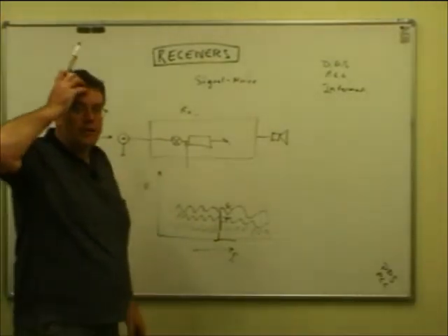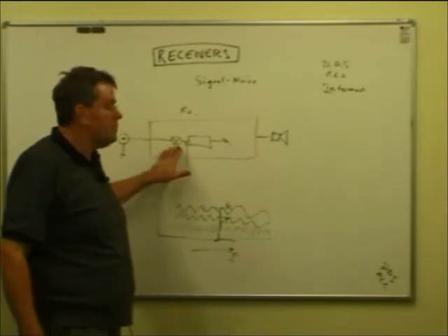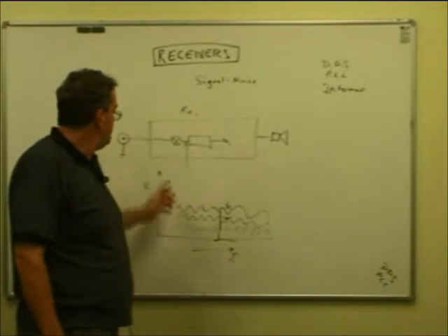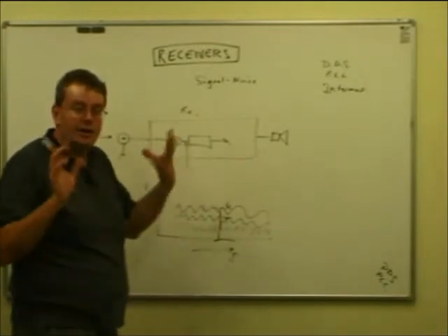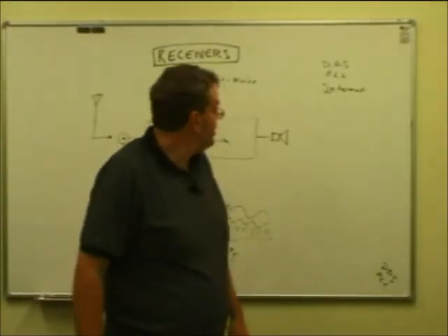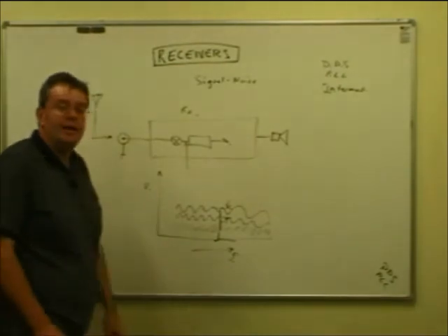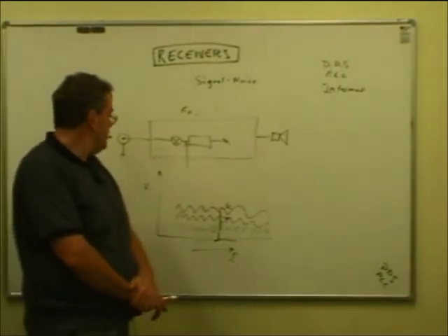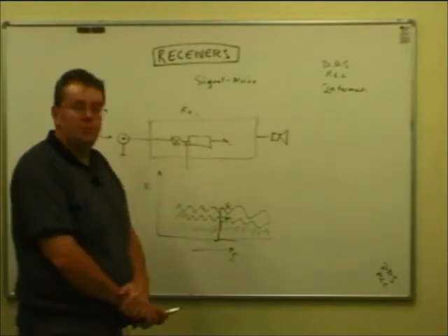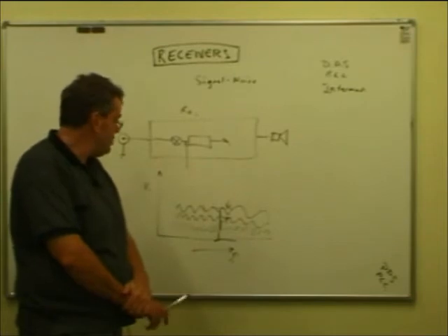Well, there are advantages. When you have amplification ahead of the mixer, if you start amplifying strong signals and the mixer has been hit by a variety of strong signals coming down the aerial, its performance can deteriorate. And I'll come on to that when we talk about intermod. So there can be advantages to removing the amplifier, and you do that in situations where the signal coming in from the aerial has so much atmospheric noise added, there's no point in giving the signal a boost before it heads on its way, because there's so much noise anyway.